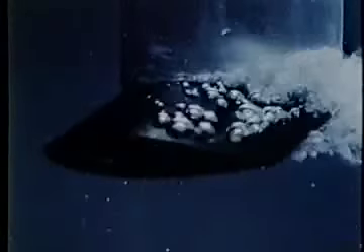With high-speed photography, we can follow the history of the same bubble as it is swept downstream. Each bubble grows as long as it is in the low-pressure region of the foil. The bubbles collapse when they enter the higher pressure region near the trailing edge. Individual bubble cavitation is characteristic of forms with gentle pressure gradients, such as those on this foil with a well-rounded leading edge.